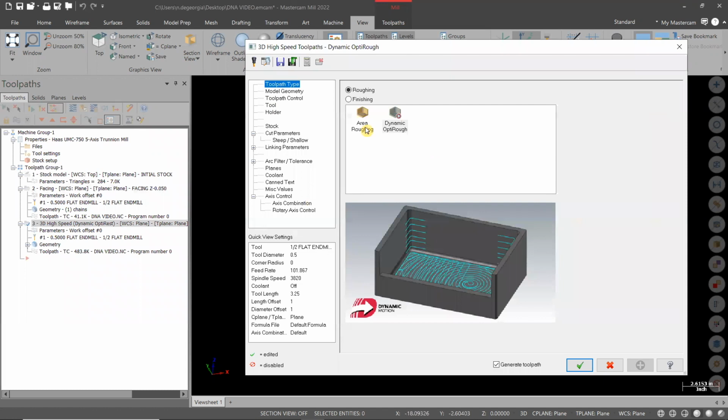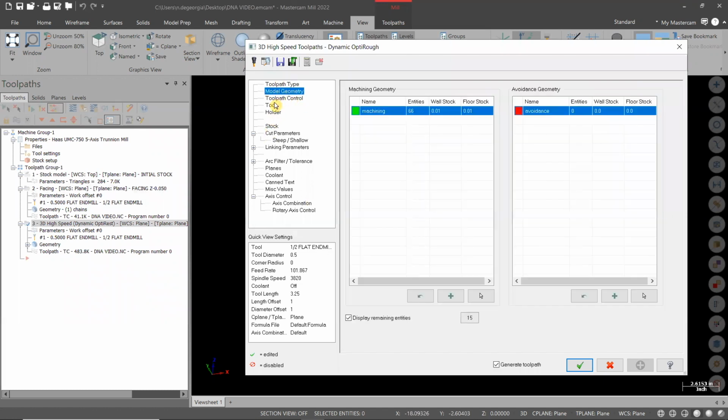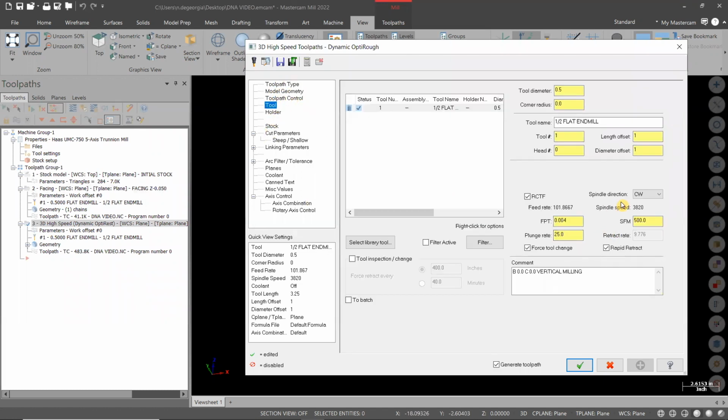After watching simulation, I realized that my feed rate seemed a bit too fast, so I'll go back and make an adjustment. After the adjustment, I'll check it in simulation again to make sure that everything looks as it should.